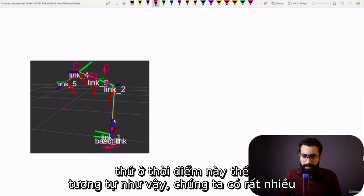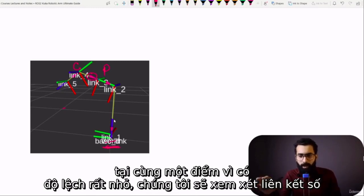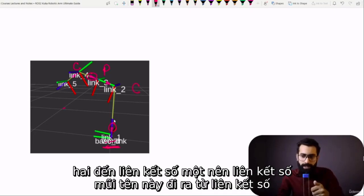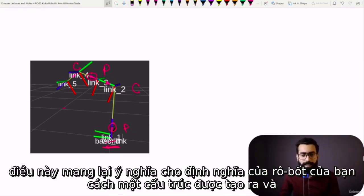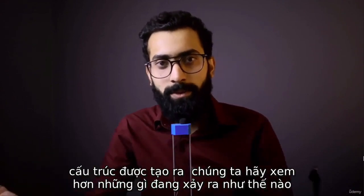Similarly, we have a lot of things at this point. Base link, world, and link number 1 are all written at the same point because there is a very small offset. Link number 2 is a child because this arrow is coming out of link number 2 to link number 1. So link number 1 is the parent, and for link number 1, the base is the parent. For the base, the world is the parent. That's how a structure has been created, which gives meaning to your robot's definition for the simulation. We'll see the URDF now to understand better how the structure is being created.